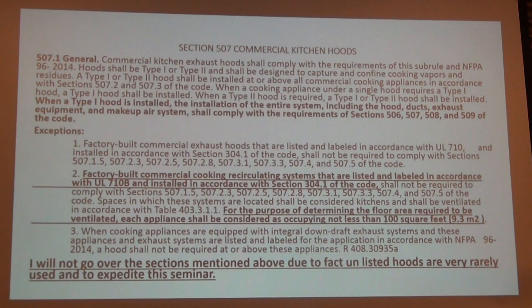We approved a Crave, it's called Crave Hot Dogs. I believe they're a chain out of Florida. We had one open in Canton, and it was the same situation. I'm talking roller grills, a couple of turbo chefs, no hood in the kitchen. But it was per plan, they already planned for it. They had like a 150 CFM continuous operation fan in the kitchen. Yeah, but how many appliances did you have? I think there were 2 Merry Chefs or 2 turbo chefs, and then a roller grill. Okay, 300. That's it for the cooking appliances. That's 300.